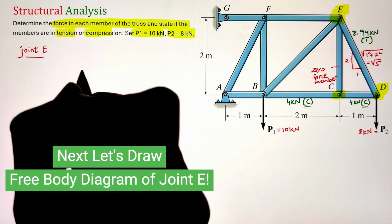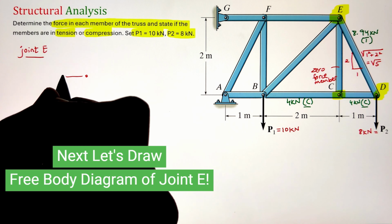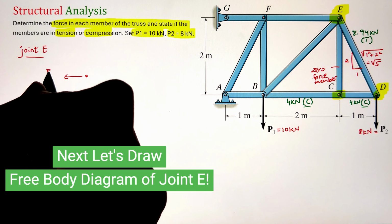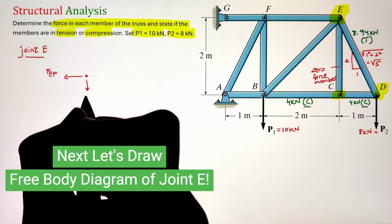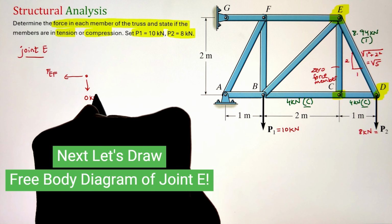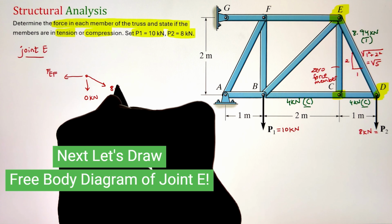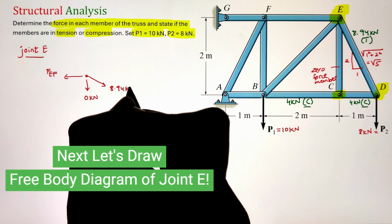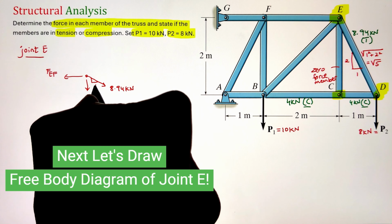Now, once we have figured out our joints D and C, we can go ahead and calculate the forces at joint E. For joint E, there are four members connected. So, in order to solve this, at max I just need to have two members that are unknown. Since we have already calculated the force in the members CE and DE, we can identify our forces in members FE and BE.